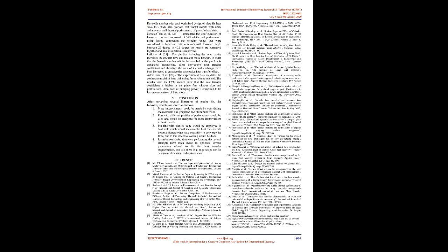The final observation is that the optimum ratio of distance between fin and spacing ratio develops maximum heat transfer characteristics in the inclusion of impingement flow. Su Minhoi et al. 23. The study represents fractal shaped inserts in a plate fin heat sink to enhance convective heat transfer. The increase in heat transfer is analyzed by varying the thickness of the fractal. The results were compared by evaluating Reynolds number with each optimized design of plate fin heat sink. This study also proposed that fractal inserts with unity enhance the overall thermal performance of the plate fin heat sink.